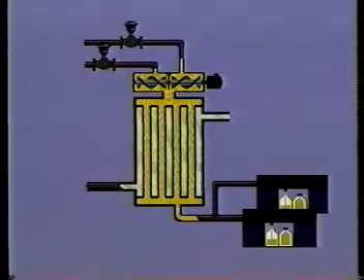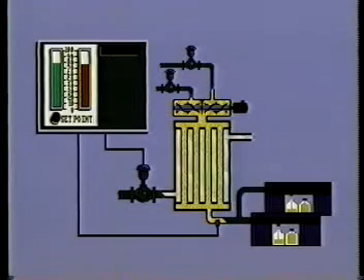The blended product would then flow through a pipeline to 2 automatic bottling machines. To control the temperature, the plant engineers installed one of the on-off controllers previously used on a batch blending tank and added a new, larger valve to regulate steam input to the heat exchanger. They soon found out, however, that their selection of a controller was a poor one.